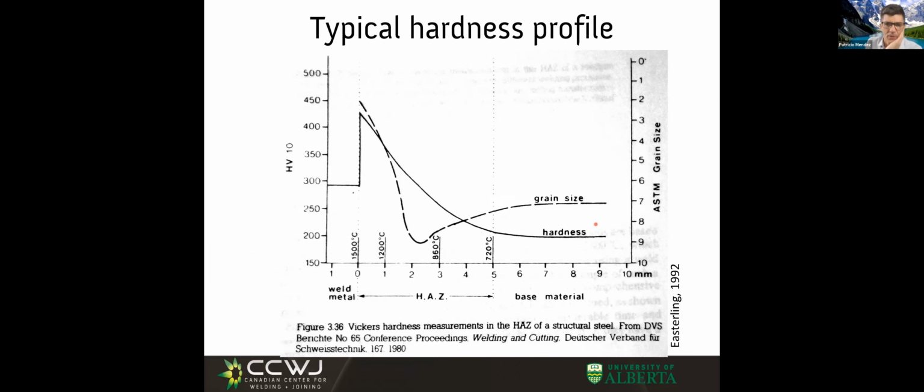So here we go. Why is coarser austenite more hardenable? I have a very interesting question. We discussed this on Thursday, but I'll bring it up again. More hardenable means it takes longer to transform. Doesn't mean it's harder. It means it takes longer to transform, which often means that in similar conditions, more hardenable is harder. But the peak hardness of martensite is the same. And the soft hardness is more or less the same.